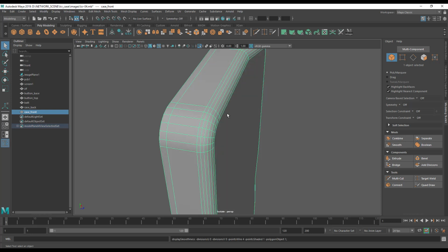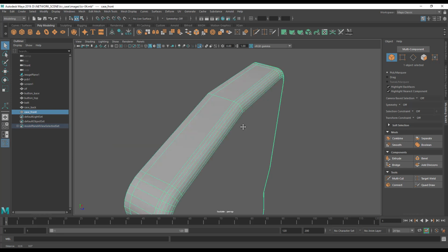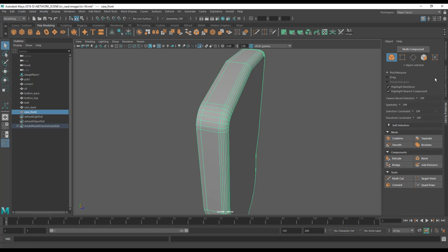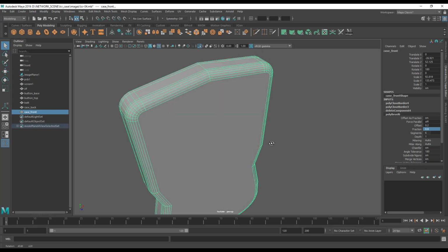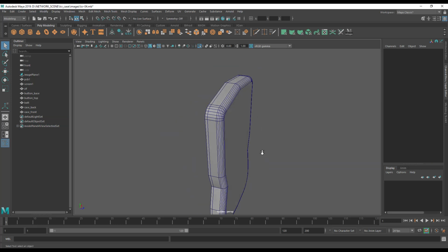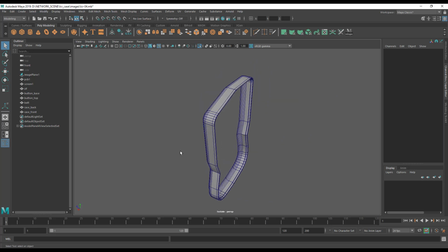Now this bevel, to me, maybe I want it a bit more in depth, a bit more depth to it if you like. So this may or may not work because we changed the geometry, but it should be able to come down here, bevel, and put the fraction to say 0.8, and yeah, that still works. Let's do a 3. Yep, no problem at all. So just a slightly bigger bevel. Now hopefully that won't be a big enough bevel for us to have to print this with supports, but I rather think not.